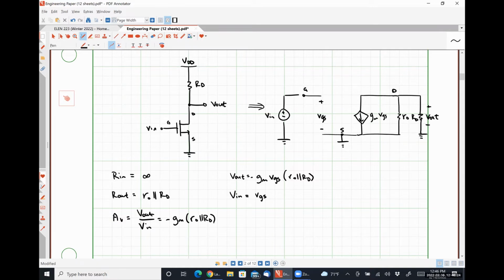Now, there is a very important distinction here between the operation of a MOSFET and the operation of a BJT, and that is operation at the edge of saturation, right? So we know that for a BJT, we can really push things 200 to 400 millivolts beyond that edge between those two, and we still effectively get what looks like forward active region operation. Okay? For a MOSFET, that isn't true. As soon as we make VDS less than VGS minus VTH, we push into triode region.